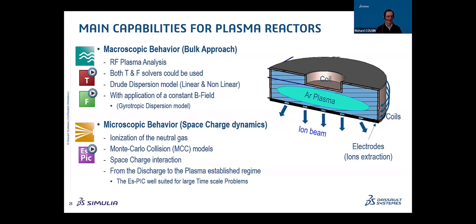For the applications regarding the microscopic behavior, we are going in this case to compute the space charge dynamics, and we are going to use CST Particle Studio for doing this. Here we are considering in the background the neutral gas, and the neutral gas will be ionized in order to extract and analyze the production of ions that you will have out of the structure.